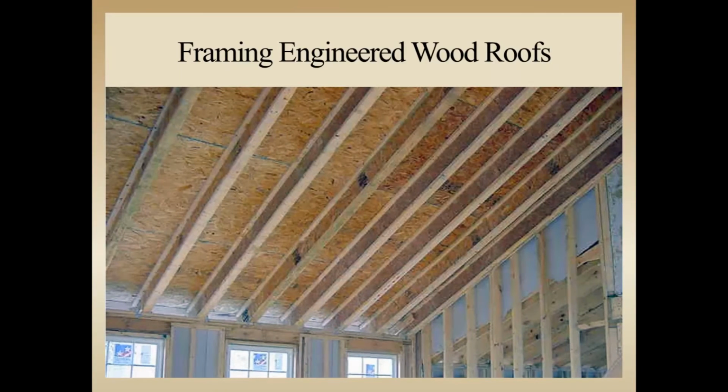In these applications, insulation will be installed between the rafters with space above the insulation to allow for fresh air to move from the soffit, from that area outside the top wall plate, to the ridge. As energy codes become more strict, more and more insulation will be required in ceilings, whether they be cathedral or attic type roofs.